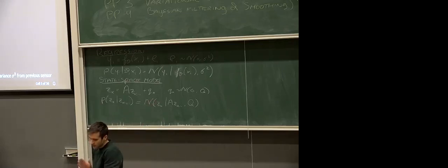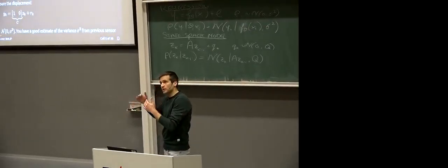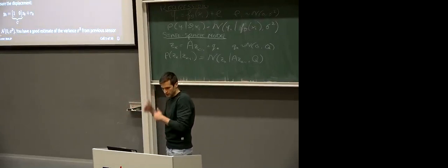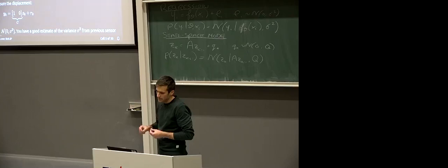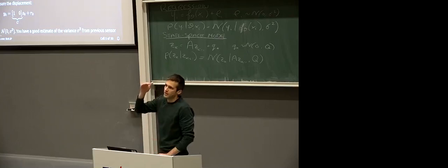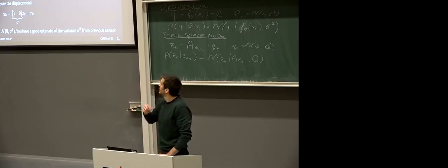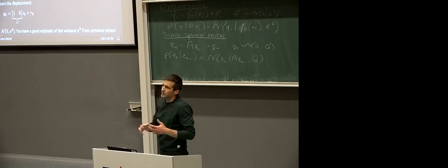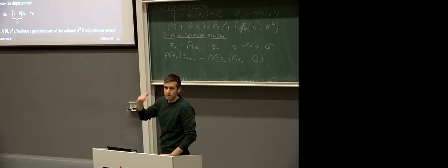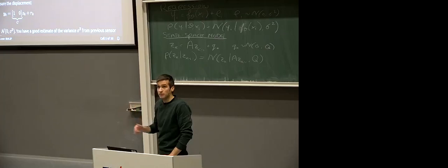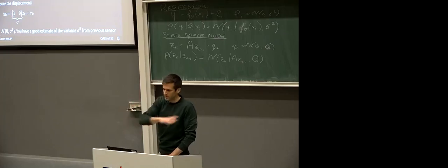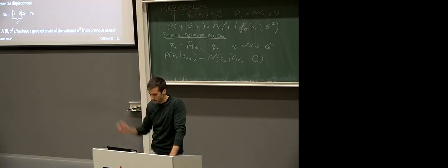State space models typically have a distinction between states: the position, and potentially more derivatives than just velocity of that particular thing that you're tracking. So for instance, if you're tracking a car, you might want to track its position, velocity, and acceleration. That's not in here. This is just position and velocity. And there are also these models for drones, which also take higher order derivatives, like jerk. And if you want to do model predictive control, you can have a minimum jerk controller, something that tries to minimize the fourth derivative of position.